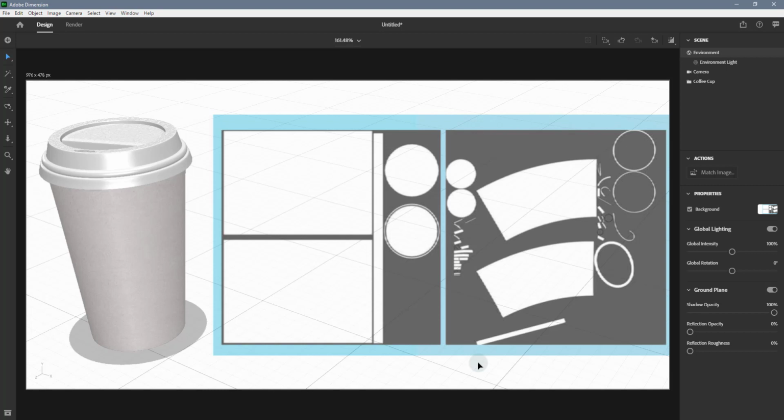Poorly made UVs. Often the result of auto-generated UVs that have never been looked at, sometimes UVs are jumbled up. The result is usually that the UVs are messy or impossible to work with. To resolve poorly made UVs, you can use the Object Generate UV menu command. Dimension will auto-generate UVs that do not overlap, though they may still have distortion and illogical seams.